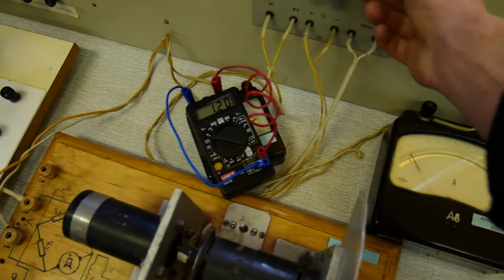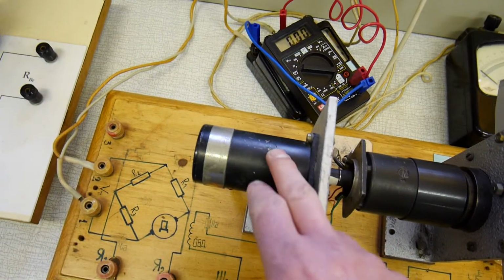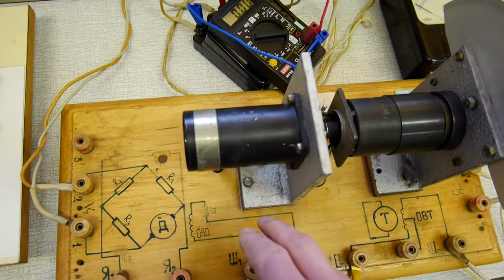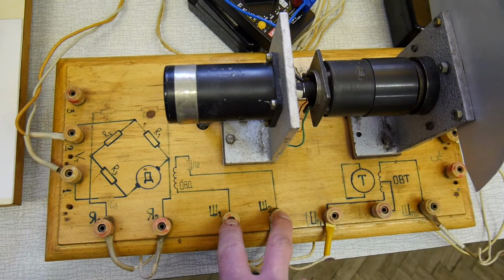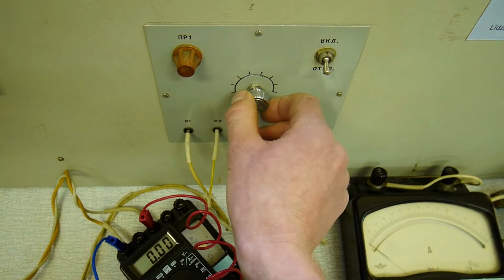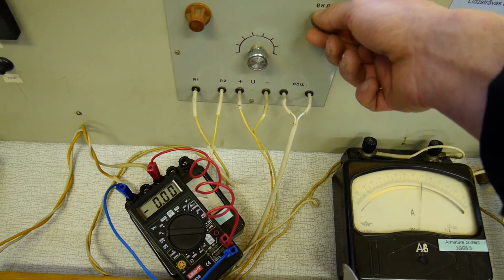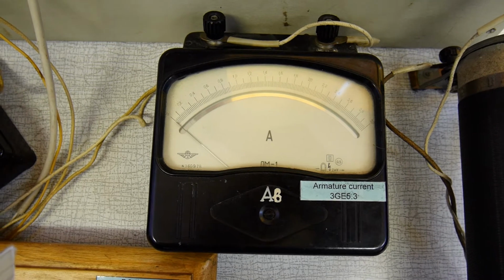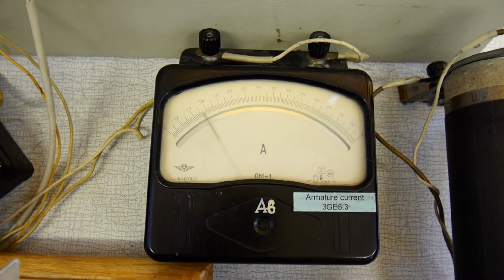Very good. So now let's see how we are able to create a motor from this DC electrical machine. In order to make a motor from this machine, we have to supply power. The power is supplied through these two wires to the armature, and through these two wires to the field winding. So I will set the voltage to the maximum, and the maximum for this motor is 28 volts. And I will switch voltage on. If you take a look at the ammeter, initially during acceleration, current will be very high, and then it will drop when the motor accelerates. Okay, now the motor is accelerating.